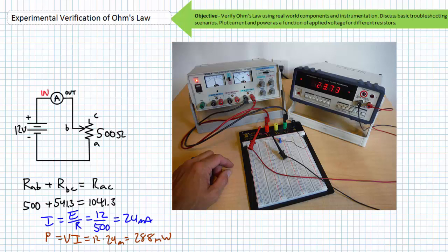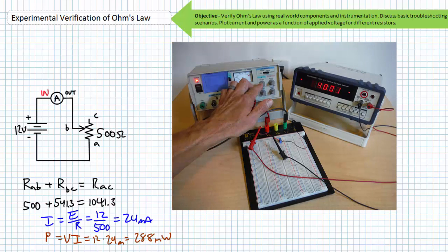You need just as much exposure to this equipment as they do, and chances are you're probably not going to set things on fire like they will. Let's continue our repeated exposure to Ohm's law with a variation on the same theme. What if I was to keep the resistance constant at 500 ohms and randomly spin the output voltage knob until the ammeter read 40.01 milliamperes?